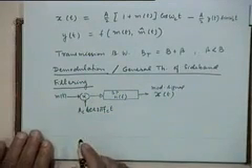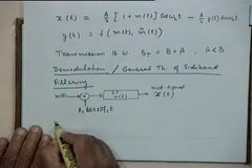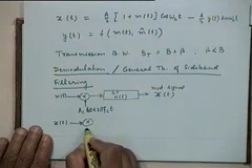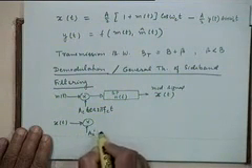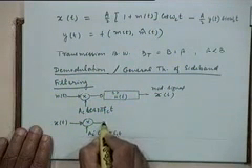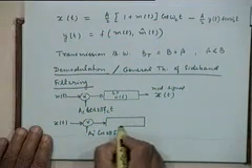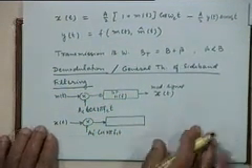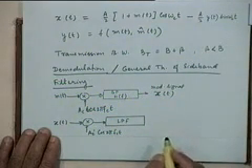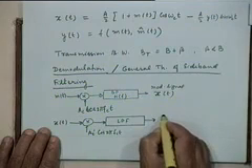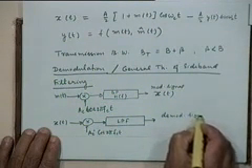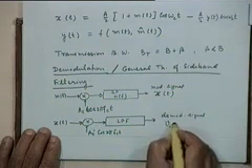And you get this x(t) here. The demodulator multiplies it with A_c prime cosine 2 pi f_c t, and for demodulation what do you normally do? Put a low pass filter here. That is your synchronous demodulation, and you will get a demodulated signal. Let us call it v_o(t).